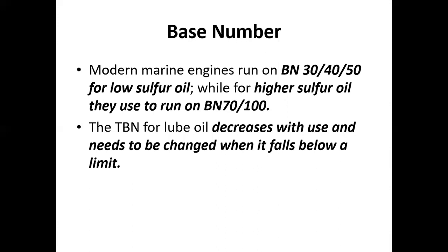Since we are dealing here with neutralization, once the base is being neutralized by the acid, the tendency is that this base component of our oil will also deplete. It will diminish through time. That is the time that we need to change our oil, because it is no longer the base component being pumped through our system, but already the acidic component, which could increase the chance of corrosion and oxidation in our system.